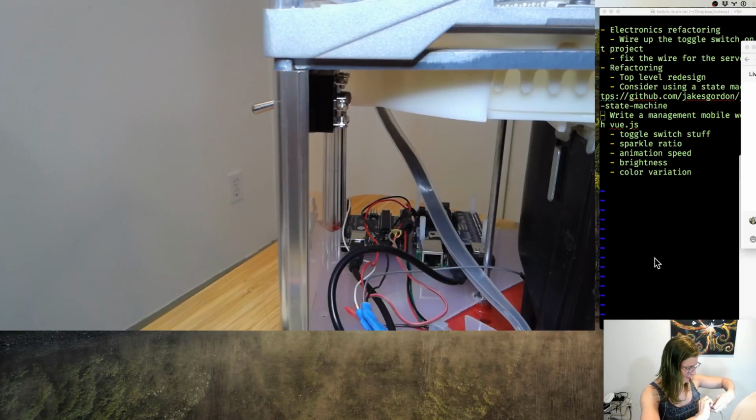Just gonna hand twist. This is something, if it was long enough, I'd just use a power drill for, but a hand twist works for now. Another thing you can do, if you just need a couple of pre-twisted solid core wires and you're gonna throw out an Ethernet cord anyway, there's pre-twisted solid core wire in there, which can be kind of useful for doing projects like these.